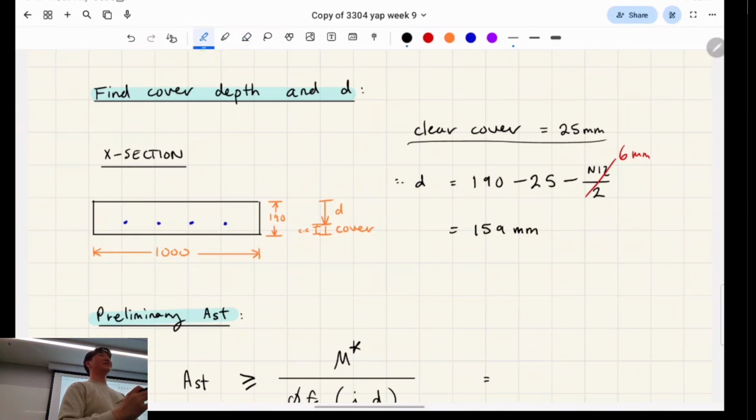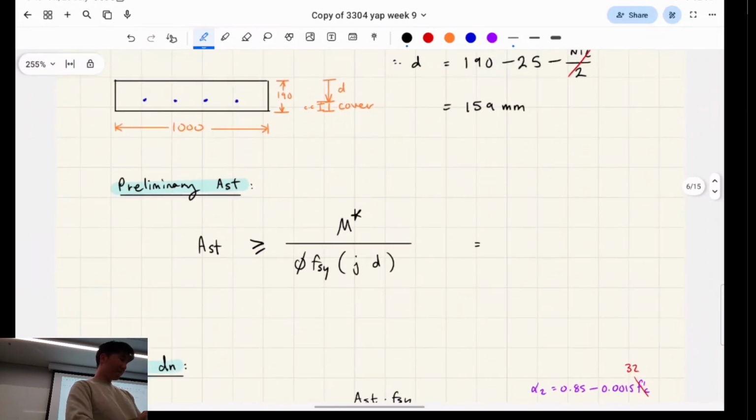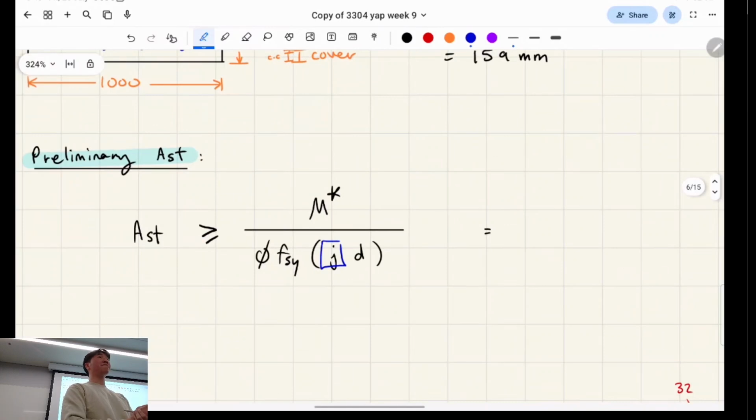So that's the effective depth, which is the same as the depth to the tensile steel because there's only one layer, right? Okay. So is anyone familiar with this formula? Okay, this is called the preliminary size formula. Basically, it's because we have too many unknowns. So we're going to have this variable called j, sometimes called x, sometimes called open box, and it's equal to 0.95 for rectangular sections. And this is a rectangular section because it's a slab, right?